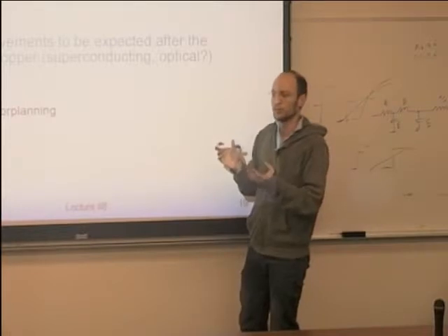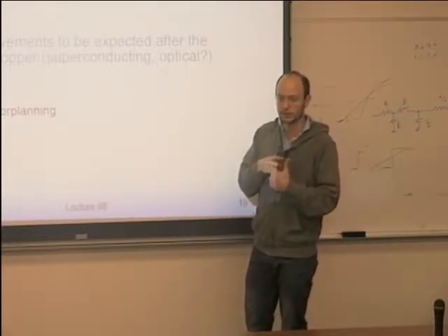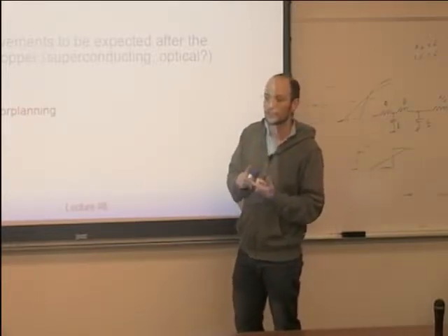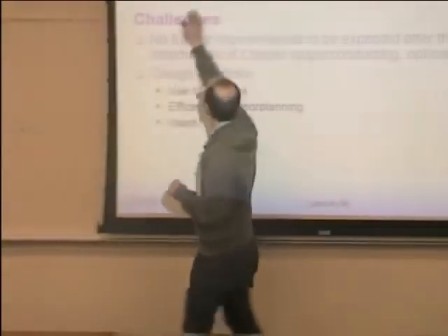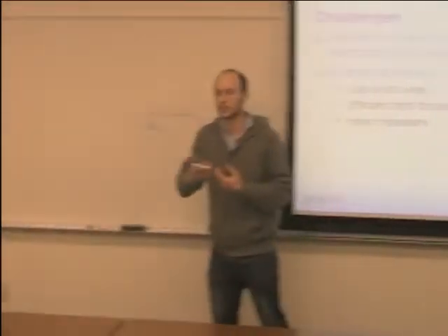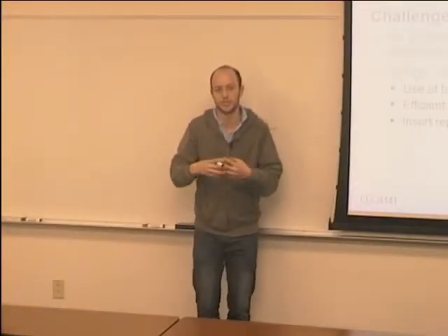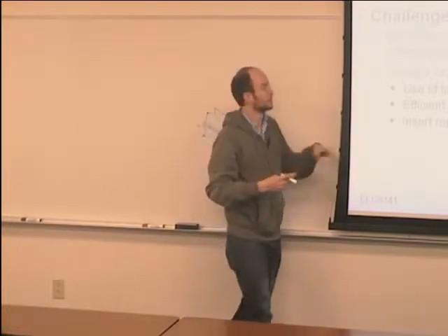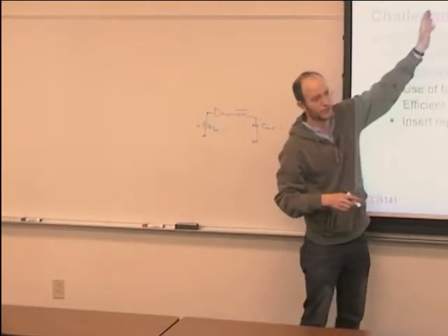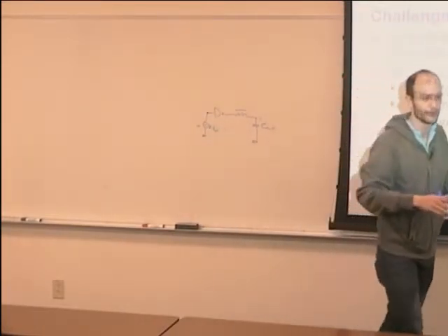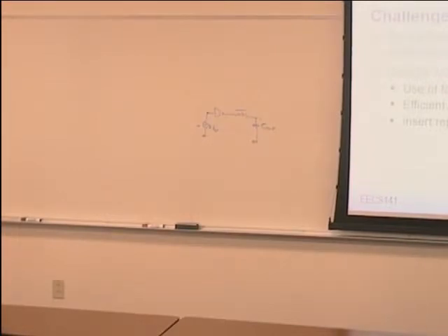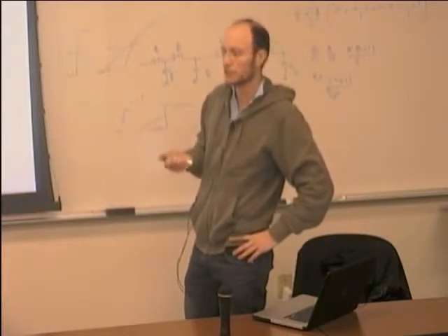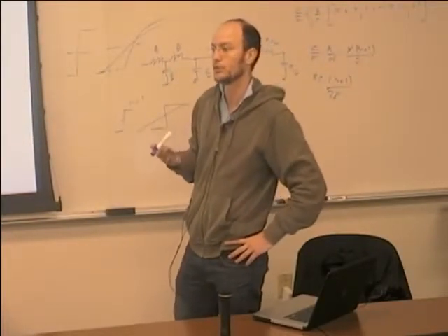There are two things that you can do, both material. One is change the wire resistivity. The other is change the dielectric, because the dielectric will change C_W. Every time you calculate the capacitance, there is always an epsilon. People are doing both things. But the dielectrics that we are using right now have a dielectric constant between 2 and 3. There hasn't been a large improvement over that. They're not silicon dioxide, which would be 4.